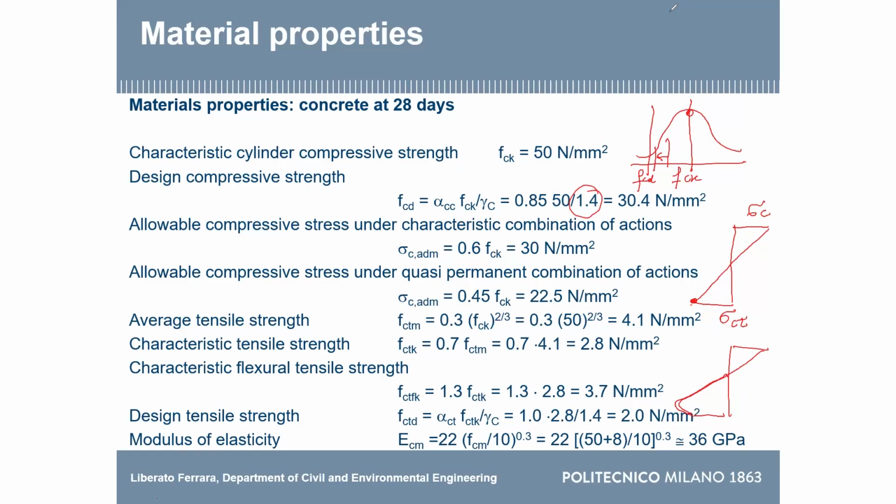That is just 25% increase. So really, you can also understand that, when you use high strength concrete, your design problem may no longer be a strength design problem, but becomes a stiffness design problem.